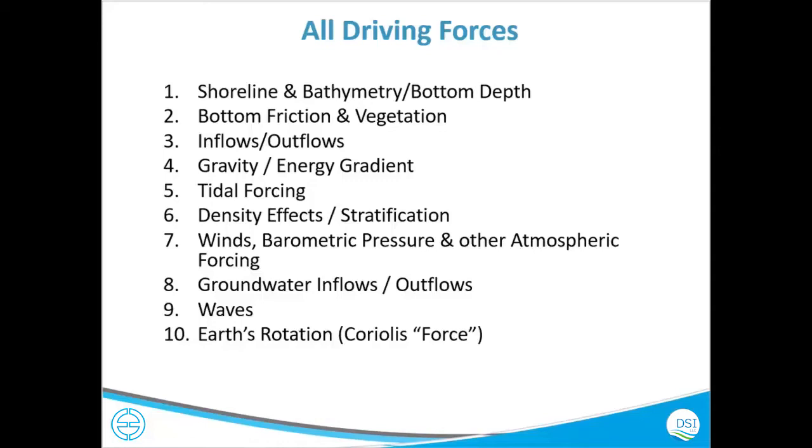And groundwater inflows, outflows, waves, and earth rotation. Earth rotation will have a very small impact if you are dealing with a smaller water body, let's say a lake. But if you have really huge oceans, then you might want to use Coriolis. So what we need to provide is the latitude of your water body. Then it will calculate the Coriolis factor. Then it will go into the momentum equation, and that's how it gets included in your model.